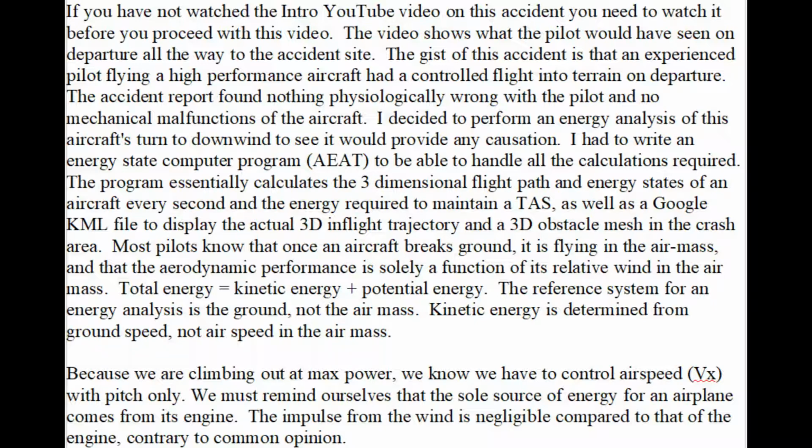Most pilots know that once an aircraft breaks ground, it is flying in the air mass, and that the aerodynamic performance is solely a function of its relative wind in the air mass. Total energy equals kinetic energy plus potential energy. The reference system for an energy analysis is the ground, not the air mass. Kinetic energy is determined from the ground speed, not an airspeed in the air mass.